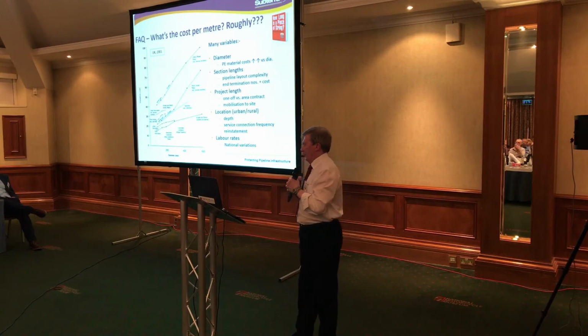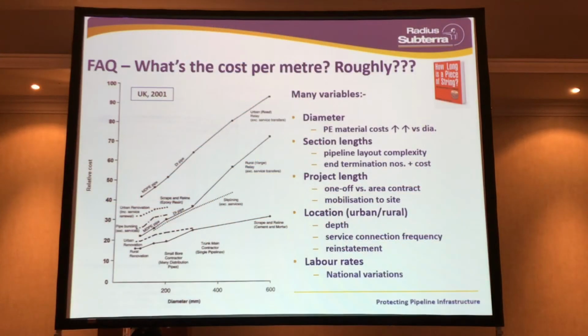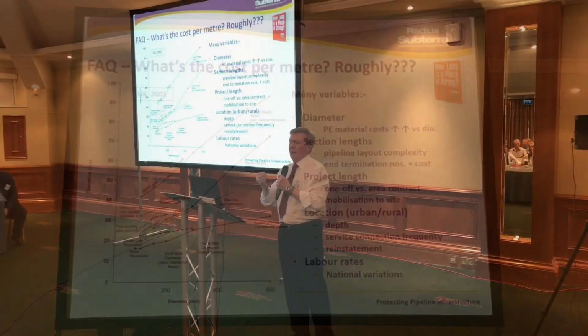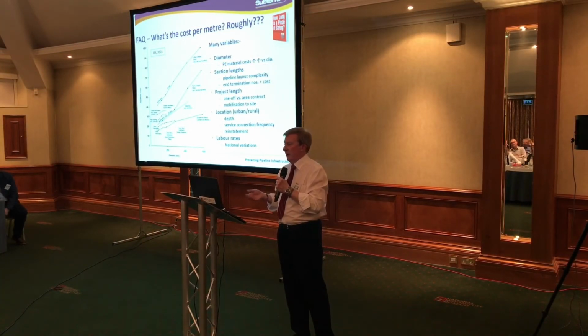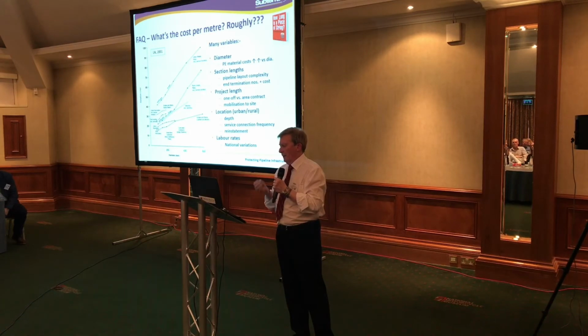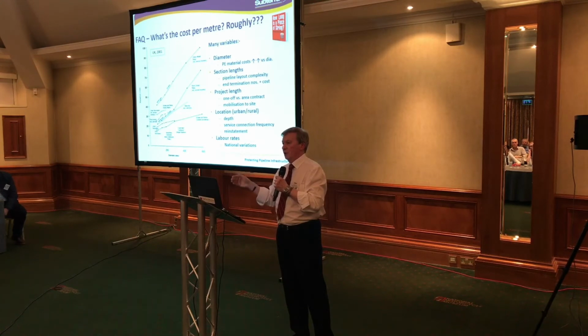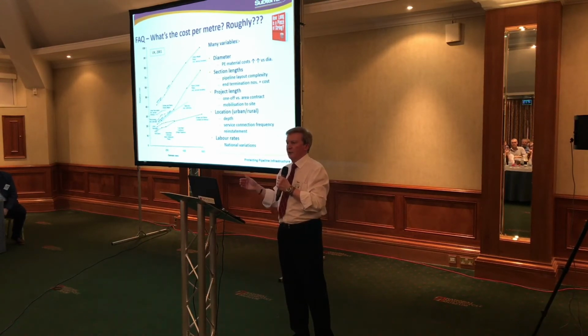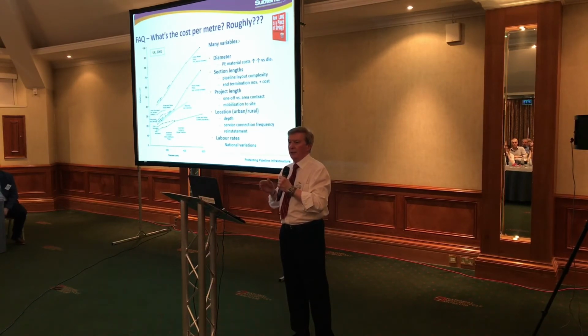And finally, and thank you for your patience, how much does it cost per metre? I tried to get an answer for this for 15 years and then just left it to the commercial guys. It depends on so many things. First of all, is the diameter or the size of the pipe, because that governs how much material you've got in the pipe. The section length, the average section length is important. The more bends you've got, the more fittings you tend to require if you can't get round them, and that can be very significant if you're talking about some of these large diameter interactive liners.